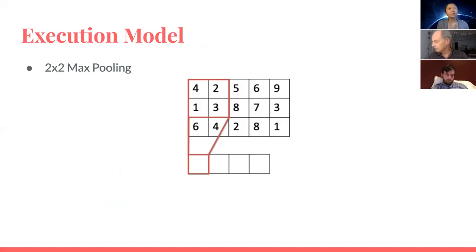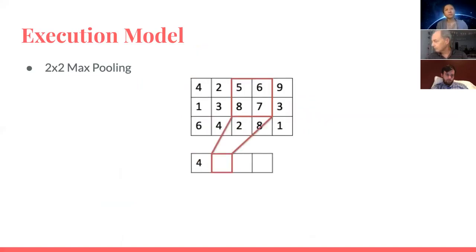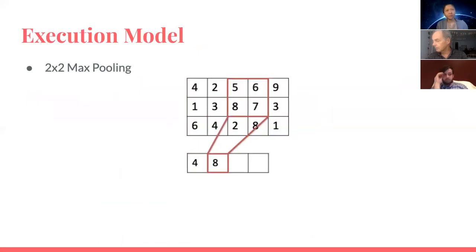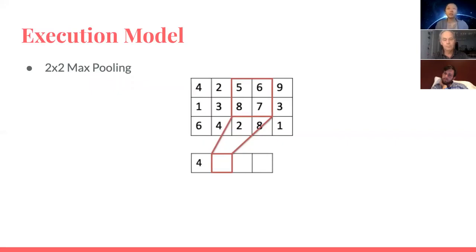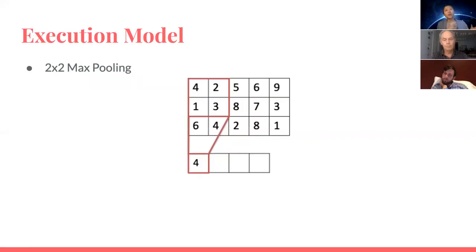And then here, I'm going to talk about the execution model of the data flow. For the pooling, what it does is pretty much just to take the maximum of these inputs. We also need to have a line buffer here because we don't want to load everything from the DRAM and compare them on the register. And then we also have certain reuse for different pixels.